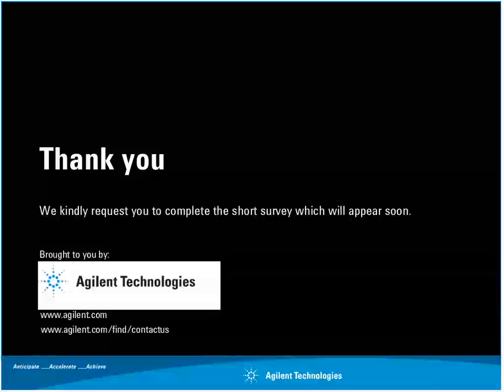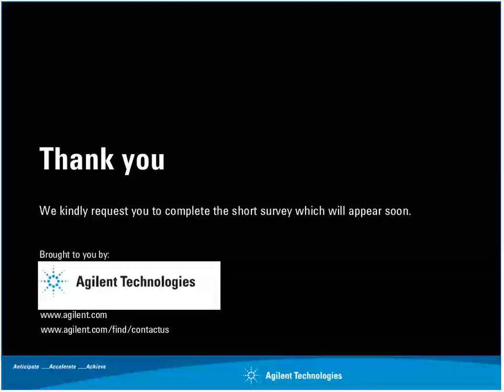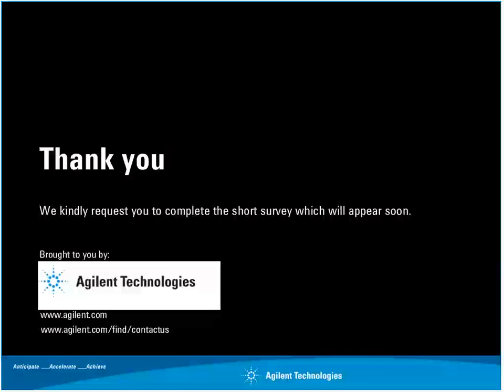Thanks, Adeline. That's a great question. So the answer to this is that the accuracy of the rise time measurement is actually a function of the sensor system rise time and also the signal under test rise time. The equation is quite complicated, so I will not provide it over here, but you can find the formula in the sensor datasheet as you can download it on the agilent.com website. There's also a graph that's showing the percentage of error that you can expect if your signal under test rise time is in the range of a nanosecond.